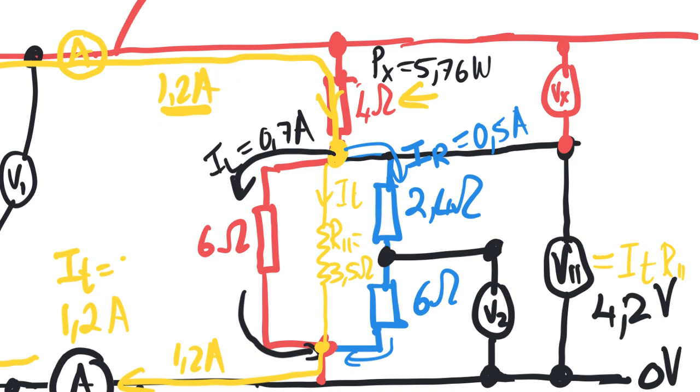But something else I want you to look at. Can you see that this is 8.4 ohms and this is 6 ohms? Well, the right-hand part of the network has got a bigger resistance, so you would expect it to draw a smaller current. And the left-hand side has got a smaller resistance, and you expect it to draw a bigger current. And it's exactly what it does. Also, if you times 0.7 by 6, I times R, you get 4.2 volts. So it's always good to just check that what you have solved actually makes sense contextually.